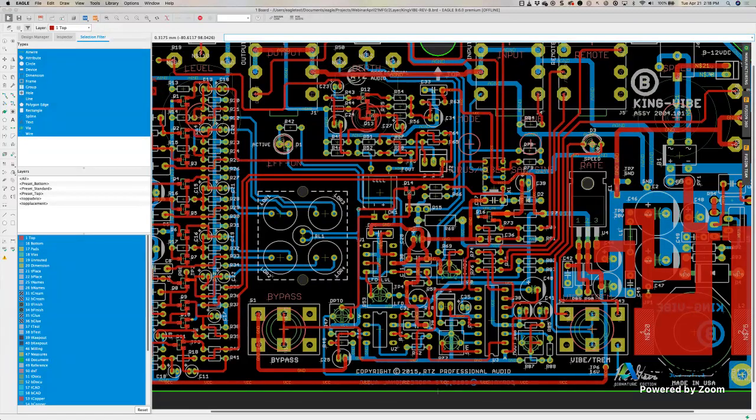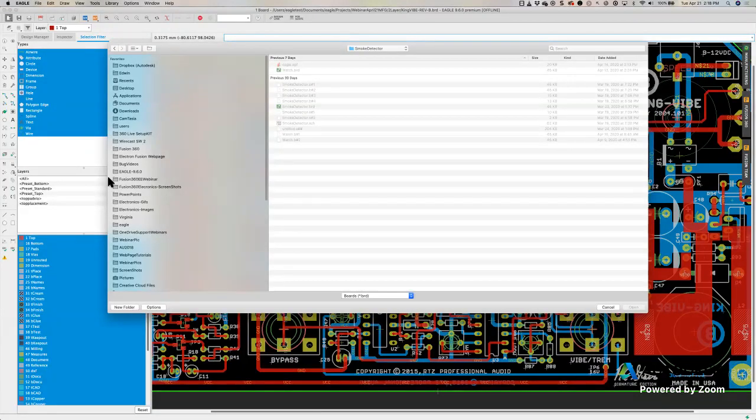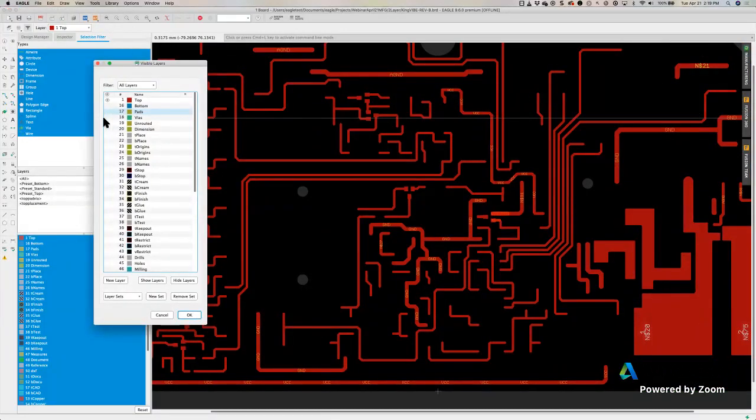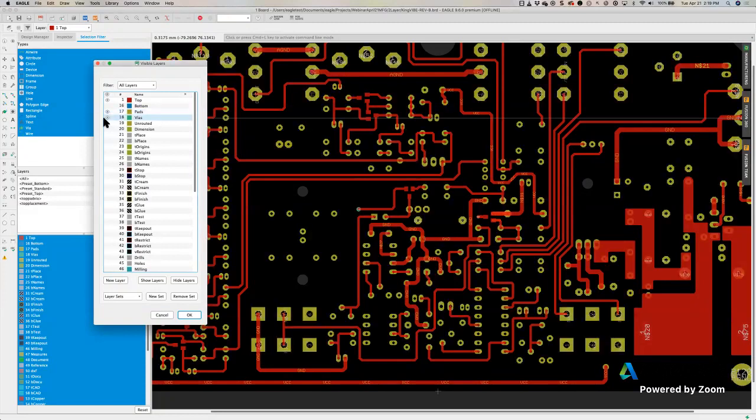It's making assumptions about your board. As you guys saw, it calculated, looking at the DRC, that it's a 2-layer template. But on a template like this, if you have anything on a milling layer, or anything on a special layer, something that's unique to the design, you can't use this simple one-click method. But we'll be talking more about that as we carry on. It's important to be aware of that. As long as there are no special layers being used or anything with milling going on, you can use this.